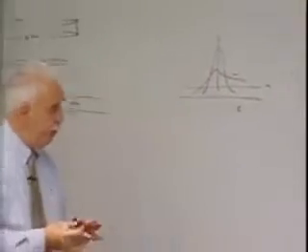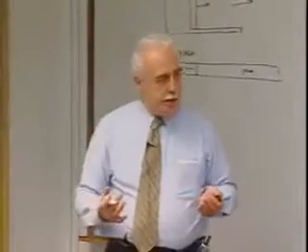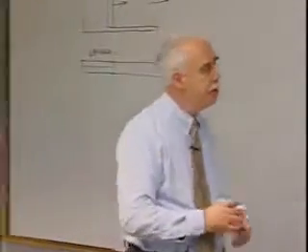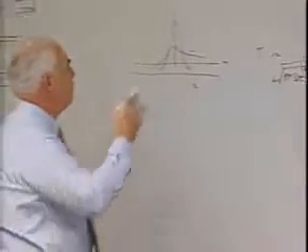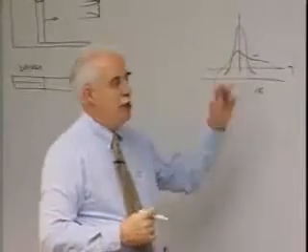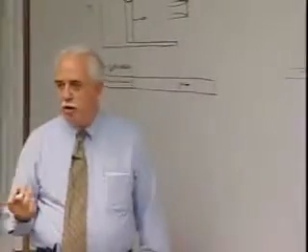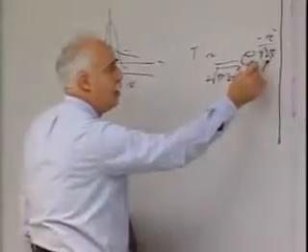Significant thing is when we talk about ablators, when we talk about tiles or thermal protection systems, this is the significant parameter. We have an extremely high temperature at the surface. The job is to keep the energy from the structure. Thermal diffusivity is the prime parameter.